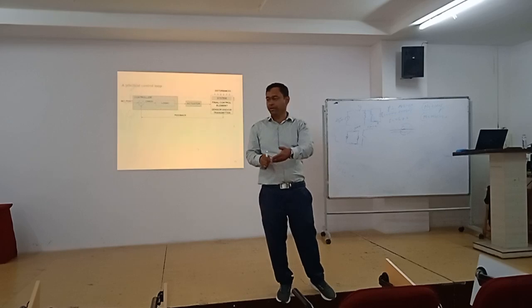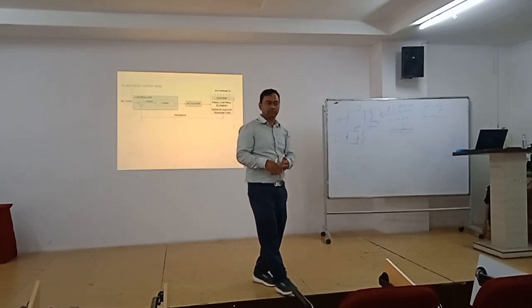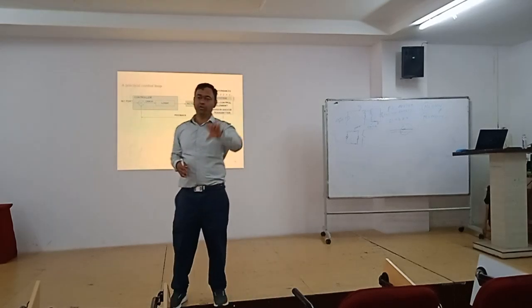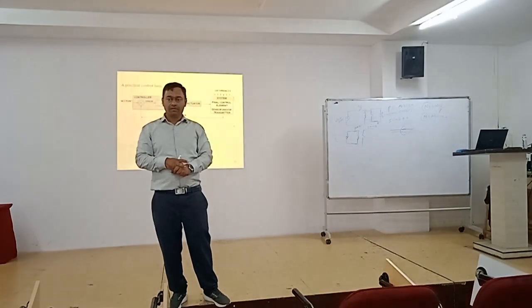So only frequency reduction will not help, because if you decrease the frequency, you also need to decrease the voltage. The ratio you have to maintain. Otherwise, the maximum flux will get saturated.